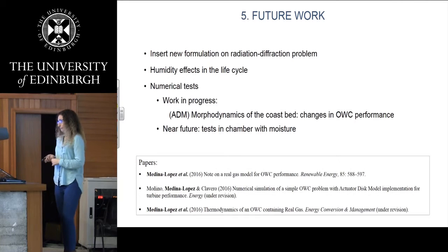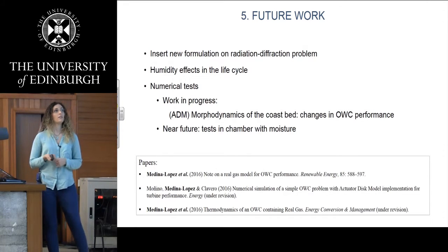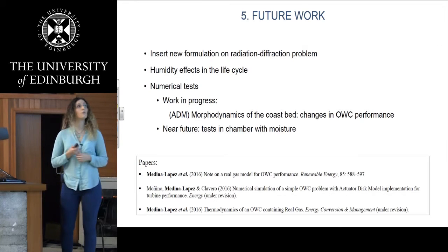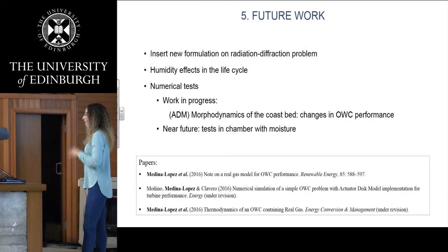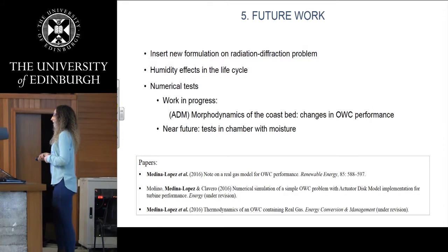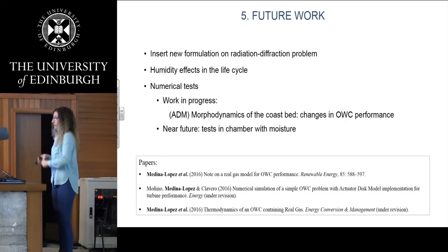Just to finish, for my future work, what I'm starting to do now is inserting the real gas formulation on the classical radiation diffraction problem to have a more exact calculation of power and efficiency, and also study the humidity effects along a life cycle of an OWC. I haven't shown that here because of time.